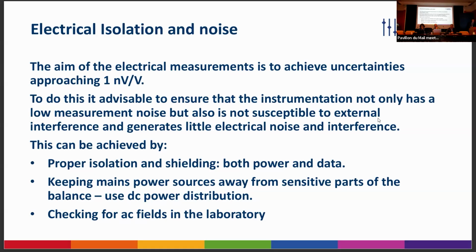It was quite interesting. We were testing the new nanovoltmeter, and the guy who was doing it said, "Look, there's 50 hertz on this thing," and so I moved the oscilloscope that he had near it, and the 50 hertz was changing. Effectively, it was just the magnetic field from the transformer of the scope getting into the amplifier. It's very important to keep these AC fields away or to stop them, but it's hard to stop them getting in.